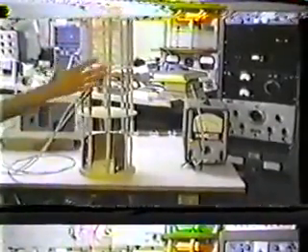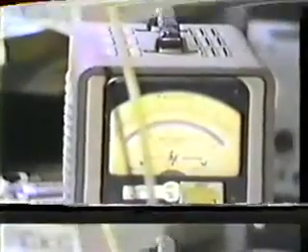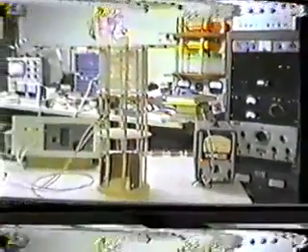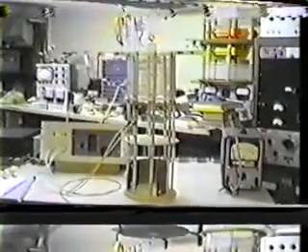So if you try to get in there to measure it, you can see by me bringing my hand near the coil that a definite shift out of resonance occurs in the meter. And as an example, I'll keep my hand very close to the coil and find the new resonance peak, and it's gone down about 30 kilocycles just by bringing my hand within 3 inches of the coil. And of course, I bring it away, I have to rehunt for the new resonant frequency. So we'll show you how these waves exist in their analog form, and Tom Brown will give you a brief introduction on the relation between the analog computer and the digital computer, and why we have to use analog computers for the study of these waves. And this will constitute part 2 of this videotape.